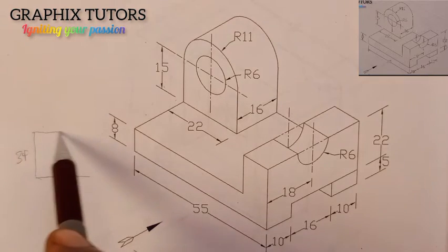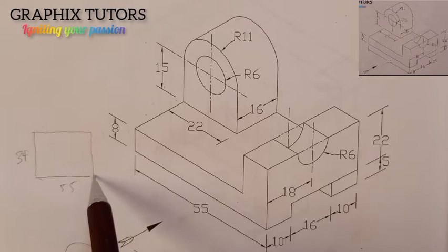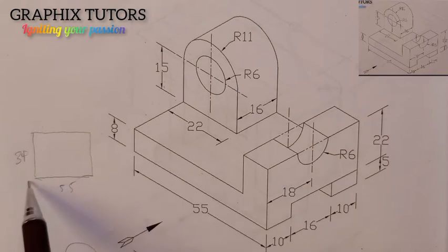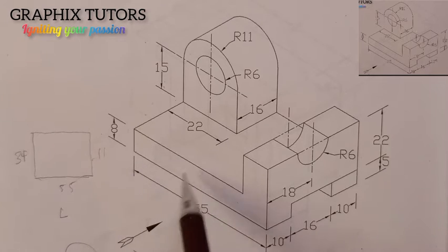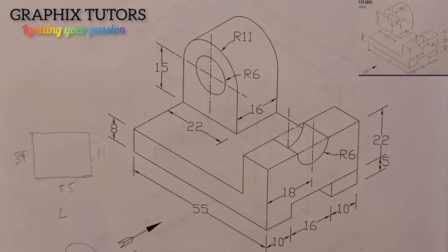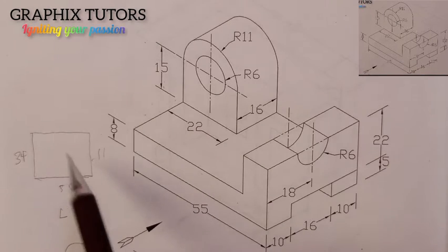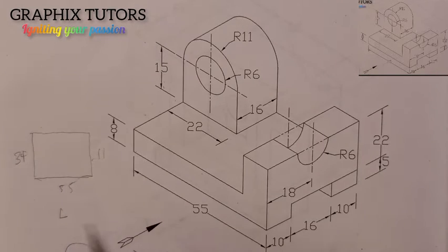So the total, where I will cover out my image from, just like I was showing isometric, is the length and the height. So the front elevation deals with what? Just the length and the height. So I'm going to pick this and I'll draw it either in the third quadrant or in the fourth quadrant to show my third angle projection. So this is what I'll do here.